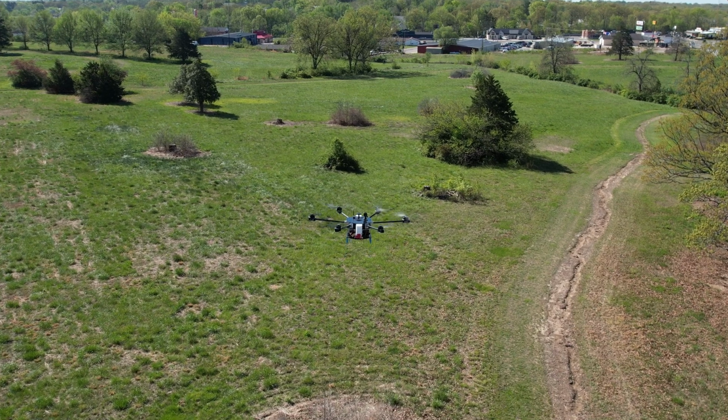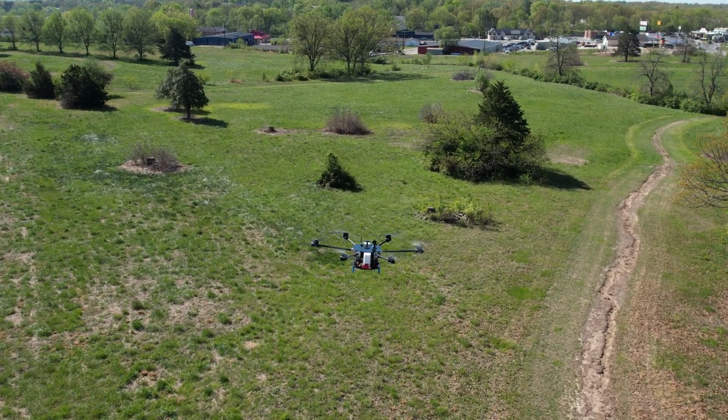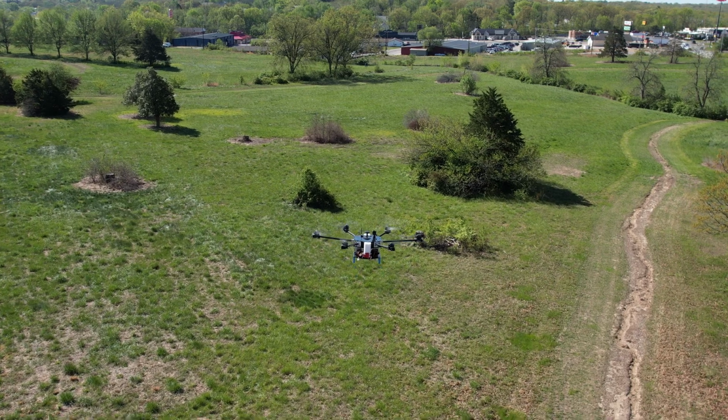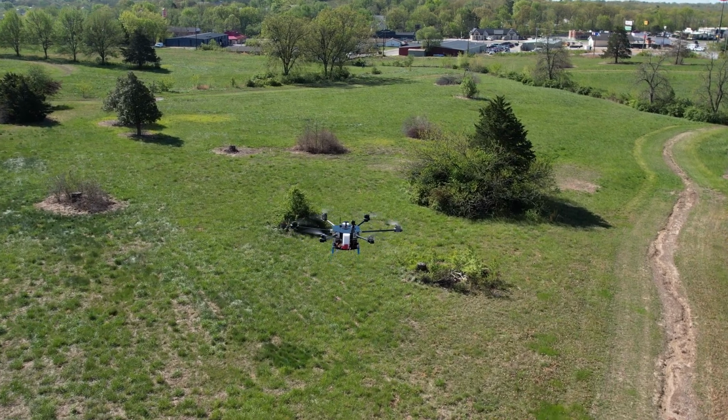In terms of the flight performance requirements, we have run the 5-mile waypoint test fully loaded for our aircraft multiple times, so we've met that requirement, and because we are a VTOL UAS aircraft, we meet all the other requirements associated with that, which include the waypoint error of 25 feet, the turn radius of a maximum of 150 feet, the angle of climb and descent of 20 degrees, being able to stay above the 75-foot AGL at all times.